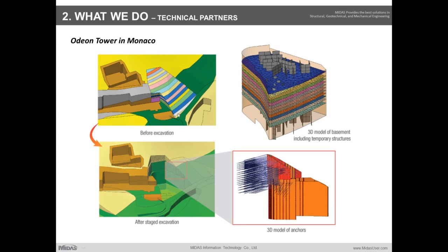So there was, I believe, a school as well as some neighboring buildings, and the engineers wanted to make sure that the excavation didn't negatively affect or compromise the neighboring adjacent structures. So as you can see, each one of these bands represents an excavation sequence. So they did it piece by piece, just to see how the nearby foundations would be altered by each stage of excavation.